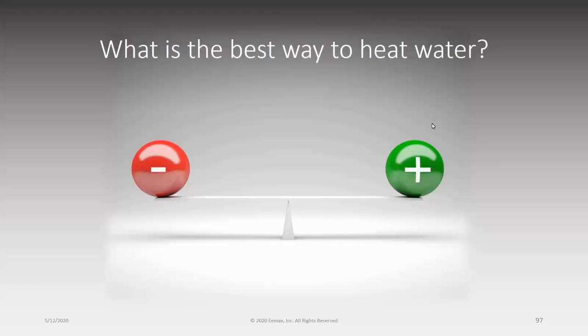You can use the right electric tankless to supplement that system. You can put it on the hot water line and provide instant hot water for the use. When your primary source reaches the tankless, it's going to sense that temperature and adjust and modulate accordingly. So you can use tankless and tanks and central systems all together to create an effective system.